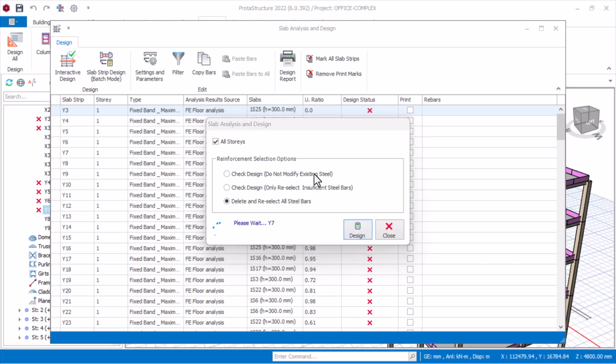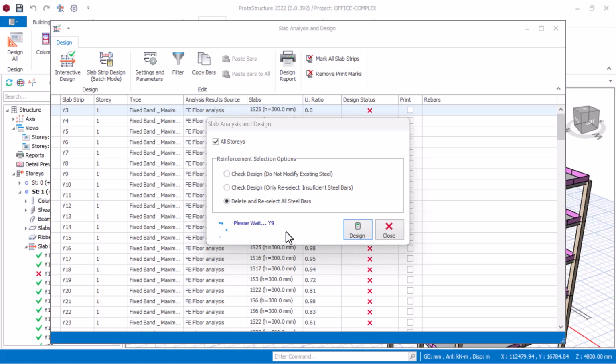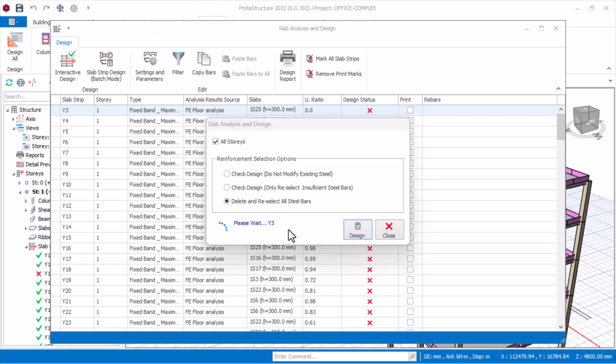So it is to design these structural members to see if the initial sizes that we assumed in step 3, where we chose our member sizes, are adequate. Don't forget I said that in step 3 we assumed the sizes. Now in this step 8, we are performing a design to check if those sizes that we assumed will be able to carry the effect of all the loads that we have considered. And now that we have performed the structural analysis, we will now check.